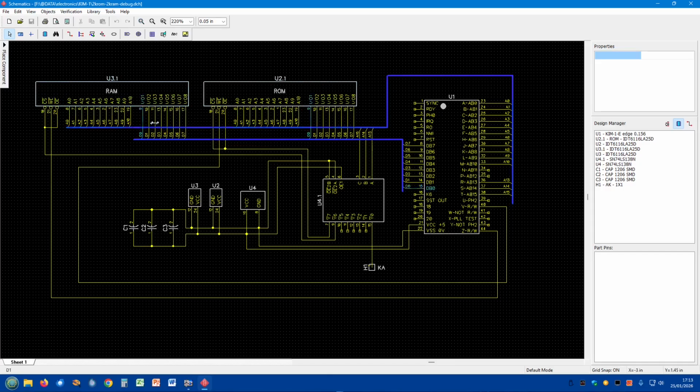The RAM is exactly the same, and that will repeat as well, but the ROM here is coming off when all 3 of these are at 1, so that's the top of the addressing range. Then Y7 will go 0, which is the chip select for the ROM. If address 13 is low, so we've got 110, then Y6 will come on and that will address the RAM. These are ROM and RAM chips that will be on the actual board. So there'll be 3 chips on the board, and that's just the edge connector.